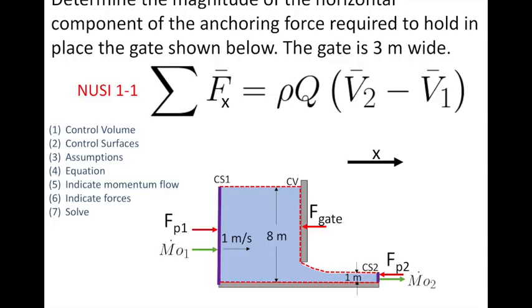So if I'm not positive which direction the force is going to be acting, I always will draw my arrow facing the right. Because when I do that, if I get a positive number, I know that yes, indeed, the force is acting towards the right. If I get a negative number, I know that my force was actually acting to the left, and that's why I got a negative number. I'm going to try to make that point a little clearer as we talk our way through these, but keeping track of the directions is really important. Again, we're dealing with vectors here. So even though we're only solving this in one direction, we still have to keep track of in which direction these different things are happening. Okay, so those are our forces. So let's take this on.